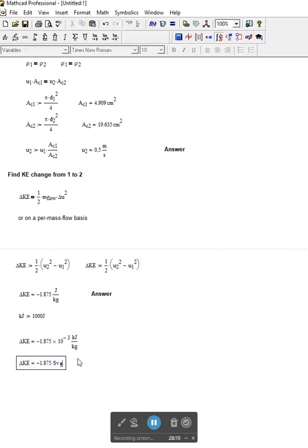So we get our sieverts, and I want joules per, now what's the unit for mass of gram? Gram, G. What happened here? This is another thing about MathCad. What is G? MathCad thinks G is the acceleration due to gravity at the Earth's surface, so that's 9.8 meters per second squared. So G is not the MathCad symbol for gram. It's GM. That is the MathCad unit for gram. And so if I do that, joules per gram, I get the correct answer. All right.